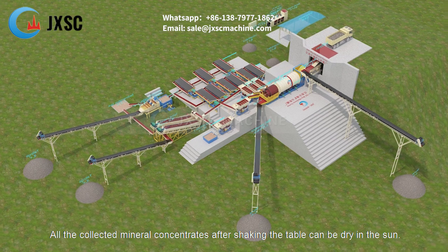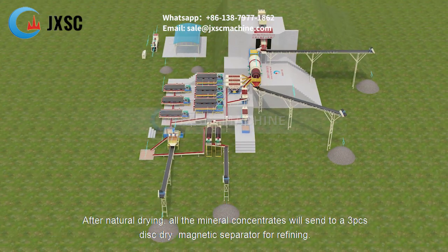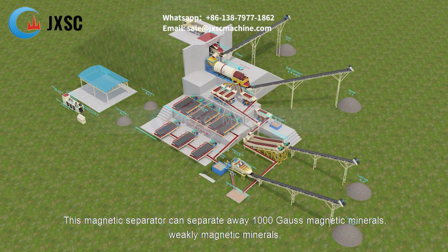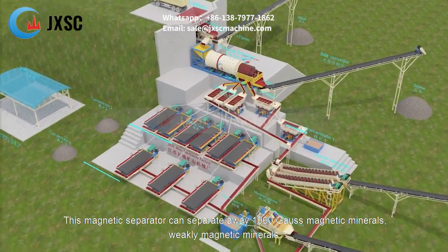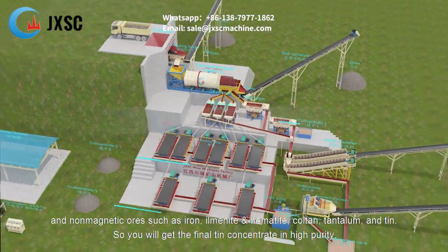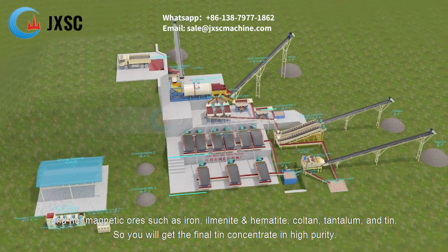All the collected mineral concentrates after the shaking table can be dried in the sun. After natural drying, all the mineral concentrates will be sent to a 3 PCs disc dry magnetic separator for refining. This magnetic separator can separate away 1000 Gauss magnetic minerals, weakly magnetic minerals, and non-magnetic ores such as iron, ilmenite, hematite, coltan, tantalum, and tin. So you will get the final tin concentrate in high purity.